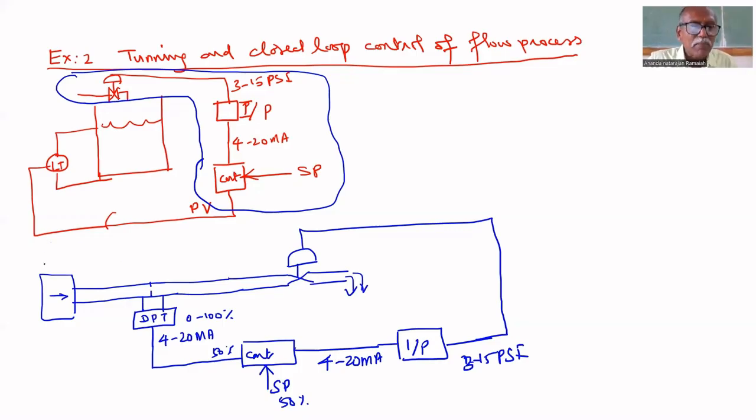It means the pump has to spend the same amount of power, irrespective of flow rate. Suppose flow rate is always 50%, the pump has to spend 100% flow rate power, but it uses only 50%. Power is wasted in the valve. This valve dissipates power. This valve absorbs some power by introducing resistance. That's why there is a large power loss.